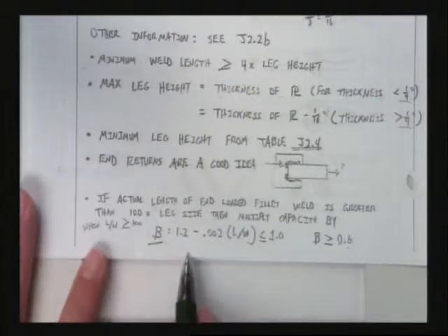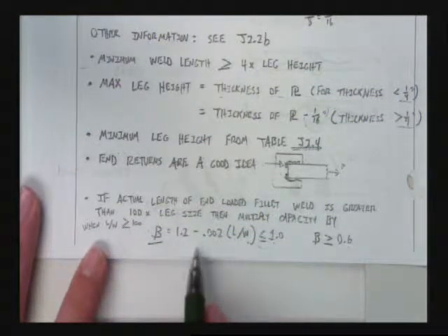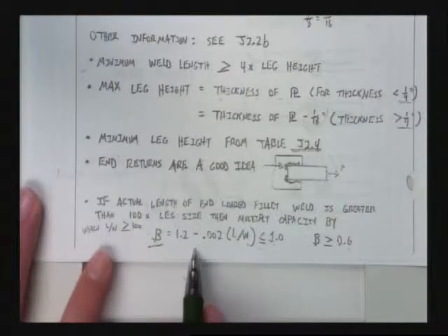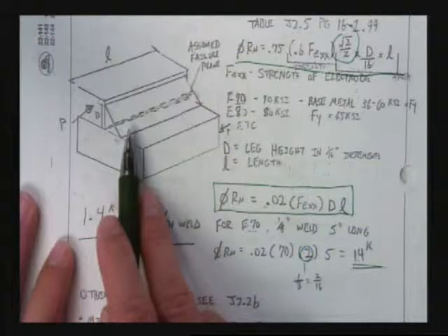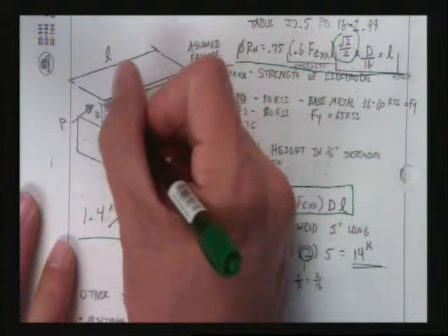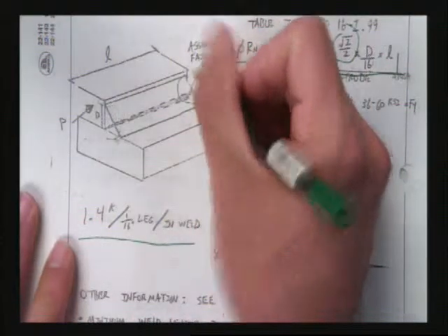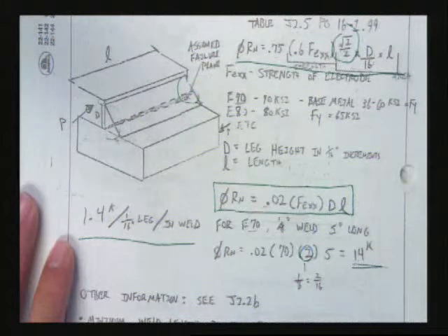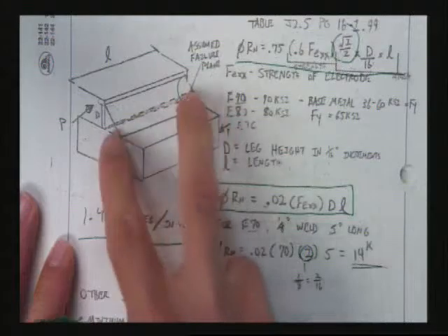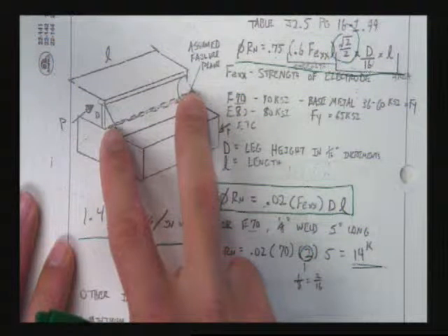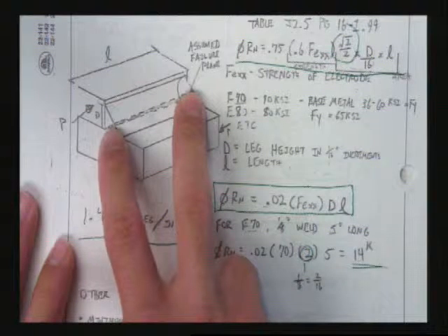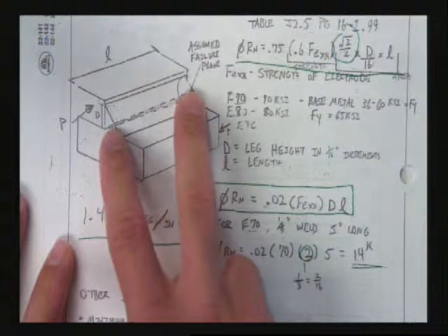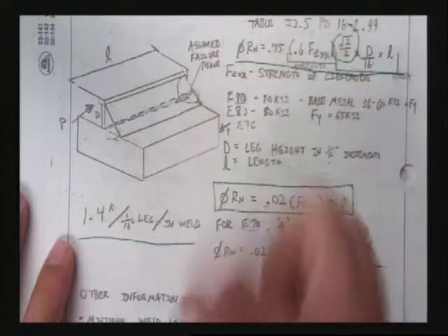This beta factor takes into account that when we load this weld to failure, we're assuming structural resiliency happens. We may overload it locally here and locally here at first, and it may reach yield at those two locations at first. You probably don't believe me right now, but it's true. There's lots of ways you can prove it. We won't talk about it, but it's true for now.